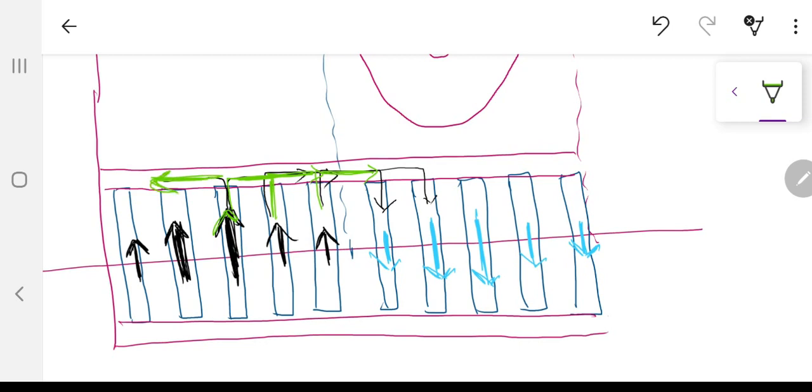So what this means is, at this particular instant in time, let me call this junction A. At this junction the end ring current is going to have the maximum value. Why? Because this bar and half of this bar are feeding the current at this point.